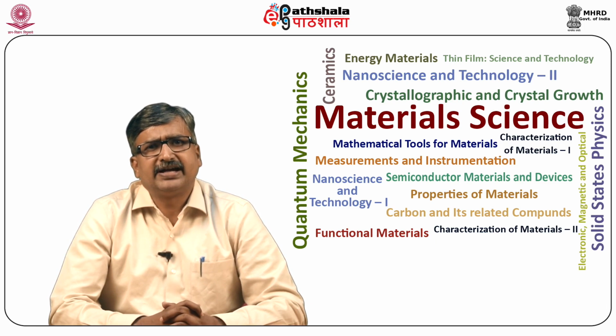Wettability can be defined as the ability of a fluid phase to preferentially wet a solid surface in the presence of a second immiscible phase. In the reservoir context, it refers to the state of the rock and fluid system. For example, whether the reservoir is water or oil wet. There are three possible states of wettability in an oil reservoir. Wettability is generally classified into three categories. The first one, the reservoir is said to be water wet, that is, water preferentially wets the reservoir rock when the contact angle between the rock and the water is less than 90 degrees.